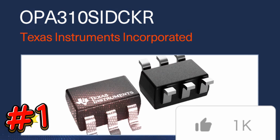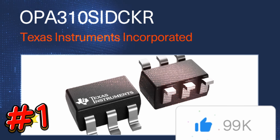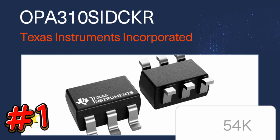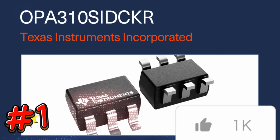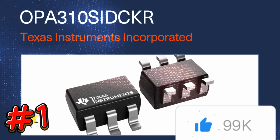The OPA310s in particular are single amplifiers with rail-to-rail input and output swing capabilities. To provide robust ESD performance, the OPA310 has a fail-safe input ESD structure with no diodes connected from inputs to the positive power rail supply.